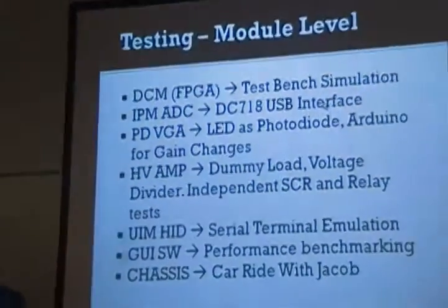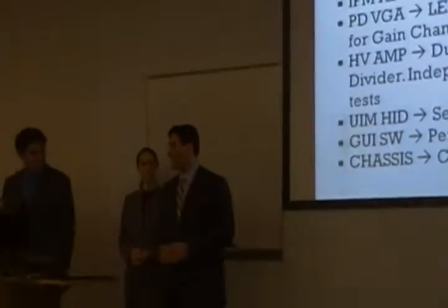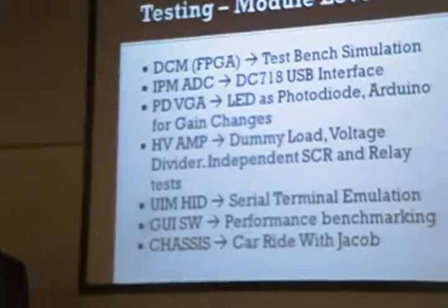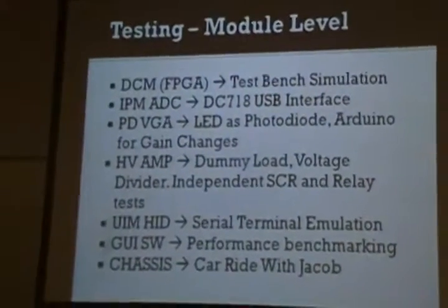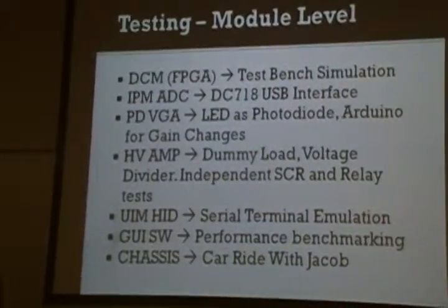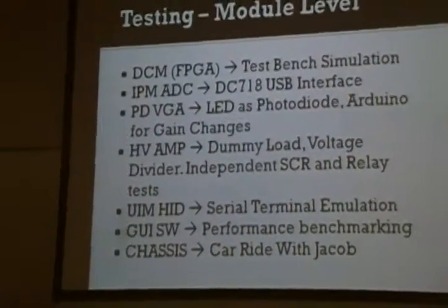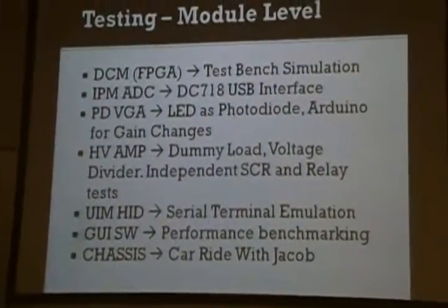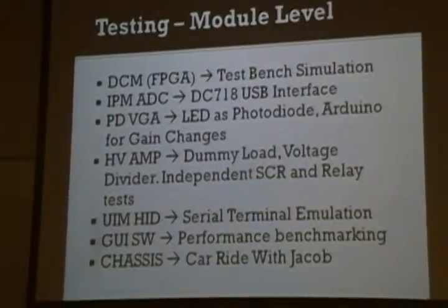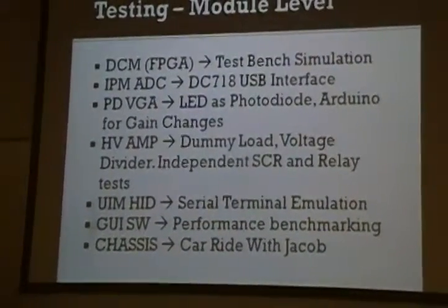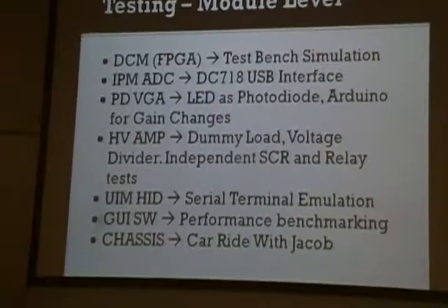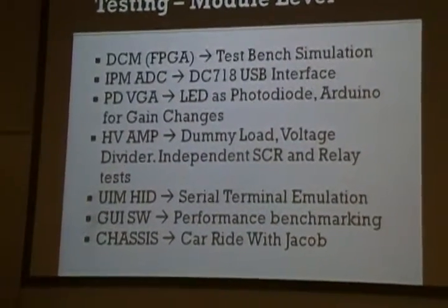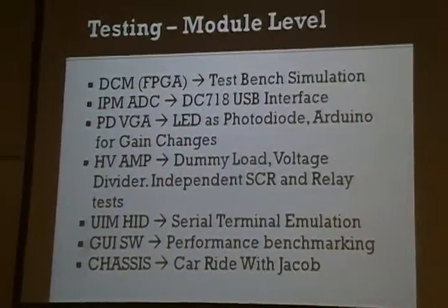But okay. So testing that, I guess, is what all you guys actually want to know. So there you go. Now that we completed our design, we needed to test it. But first, before testing the entire system, we had to break it down into modules and make sure everything actually worked before running high voltage 500 volt DC. So we started by testing things like the FPGA using test bench simulations. The input module, we ran a USB interface that would get digital values and then compare the analog values with the digital.